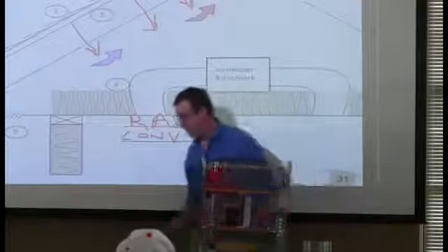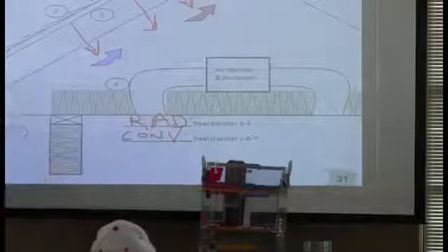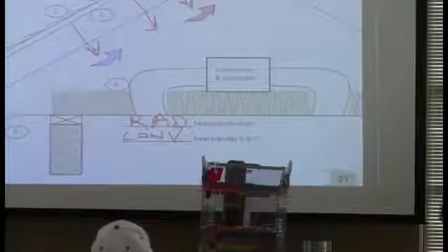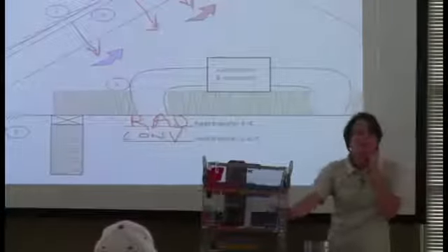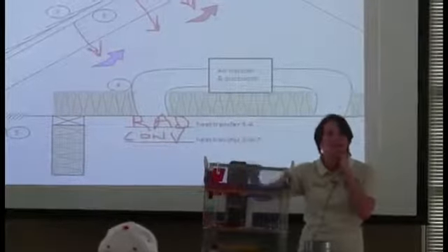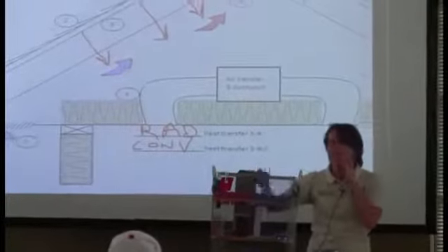How's the pressure inside the house looking? Positive or negative? Negative. All right, so let's just recap. It was neutral here. When we turned on the fan, it's negative. So that must mean the fan's sucking air from somewhere, the conditioned space.